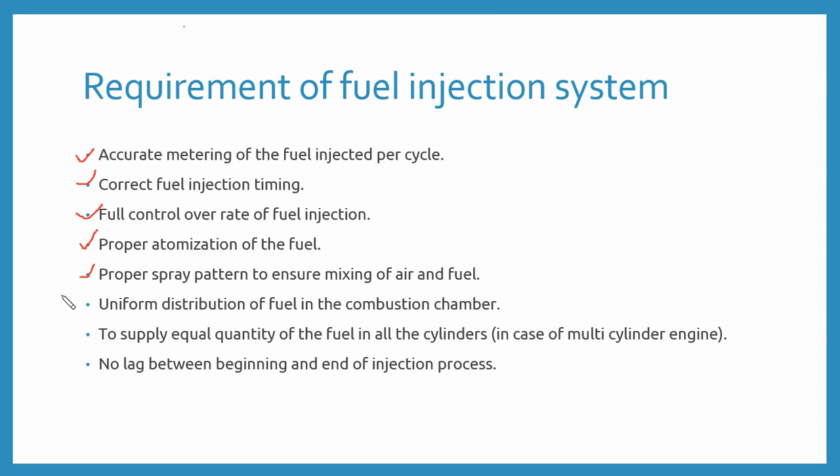How much fuel is required with respect to the air? So you need to maintain a proper spray pattern. If we spray the fuel at an angle so that it hits the cylinder wall, then the fuel is not mixed properly with the compressed air which is available in the combustion chamber. So this is not a good thing. For that reason, we need to spray in a proper pattern.